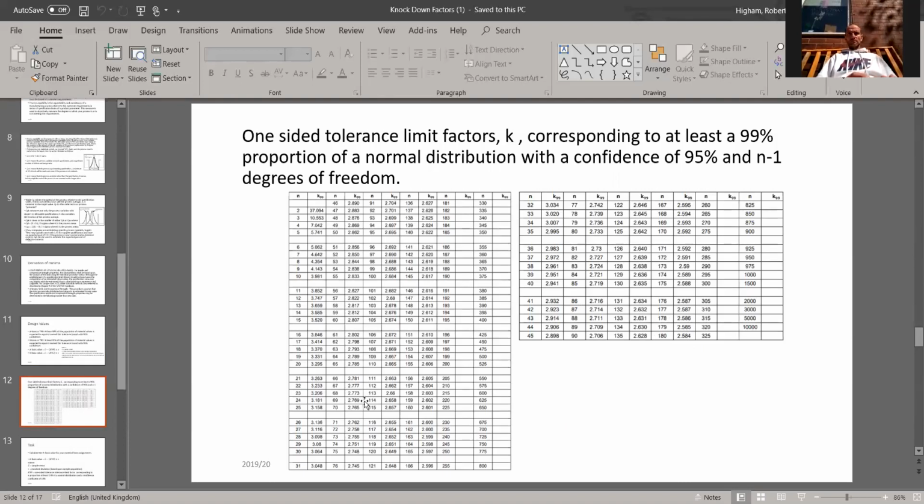So as soon as you get 2.7s, as soon as you get towards the 50 range, you're there or thereabouts. You might have heard me say before, minimum of 3 data points, because before 3, you have so few data points that the effect, in terms of confidence, is just crazy. And we used to have a rule of a minimum of 16 data points for any kind of validity, and that gives us a 3 and a bit times knockdown. Not ideal, but that's a good start.